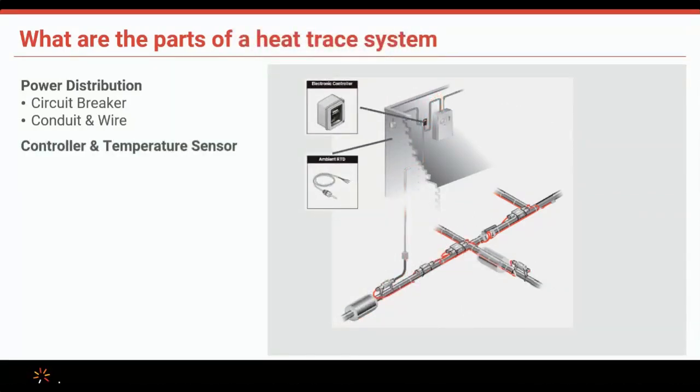In between the power source and the heat trace is a controller. Again, that could be an electronic controller with an RTD sensor, or it could be a thermostat. Do you need to have a controller? I get this question quite often. With self-regulating cable, the black and white answer is no, you do not.